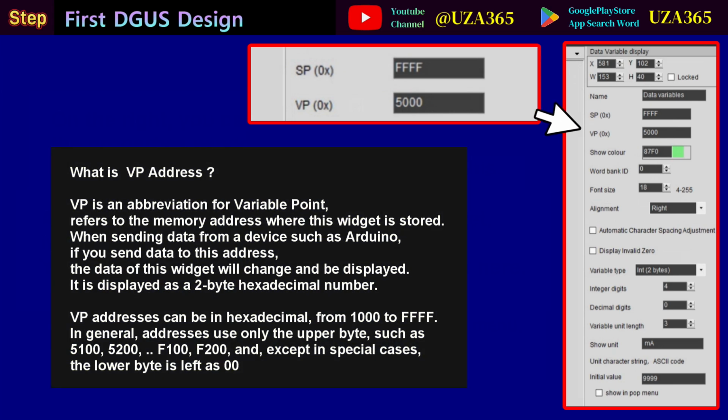VP is an abbreviation for variable point and refers to the memory address where this widget is stored. When sending data from a device such as Arduino, if you send data to this address, the data of this widget will change and be displayed. It is displayed as a 2-byte hexadecimal number. VP addresses can be in hexadecimal, from 1000 to FFFF. In general, addresses use only the upper byte, such as 5100, 5200, F100, F200, and, except in special cases, the lower byte is left as 00.